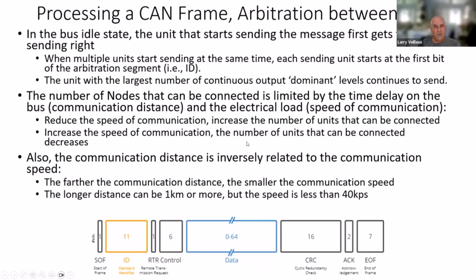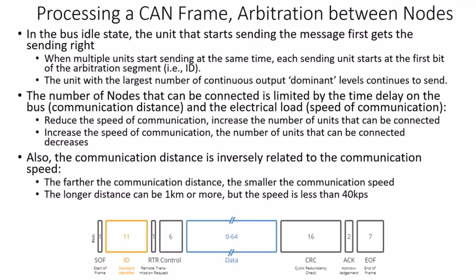It's kind of interesting. I hate to use previous analogies if you've not studied, for instance, Ethernet, but if you did study the earlier versions of Ethernet, you may have heard of the 5-4-3-2-1 rule for determining how many segments of the bus can be connected by repeaters and so on. It all had to do with the speed as well as the distance. And the intersymbol interference. Yeah, exactly. And to a certain extent, you might even say that interference is not a factor here because of the differential signaling. At these speeds, that's correct.